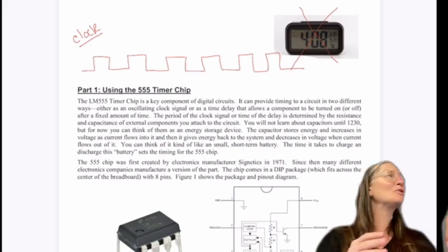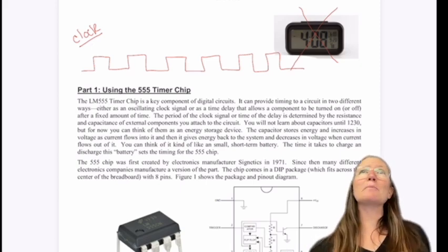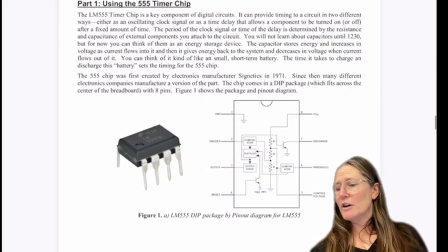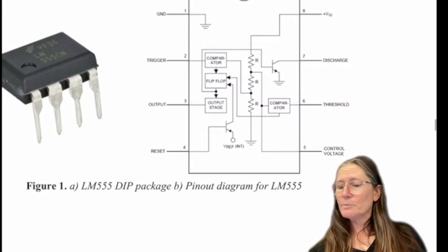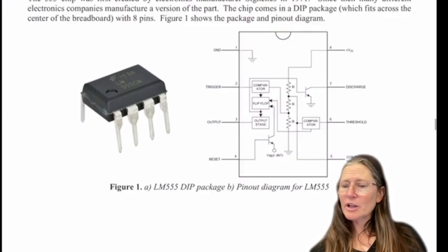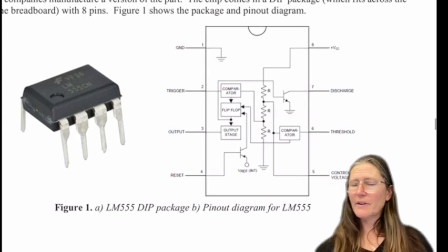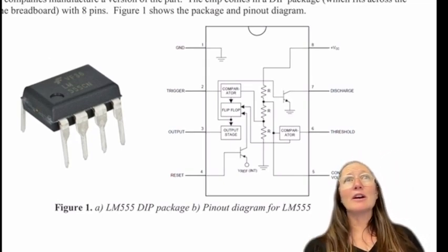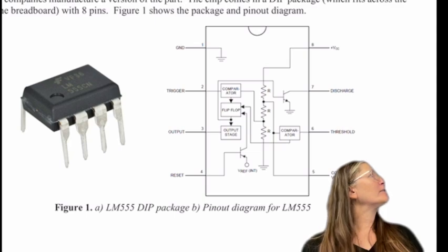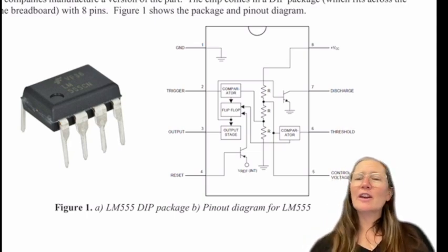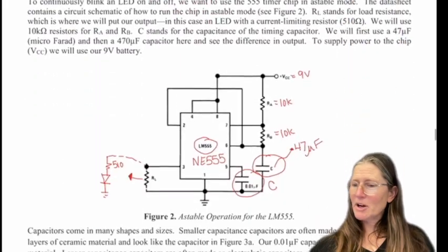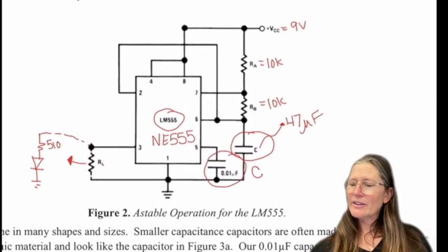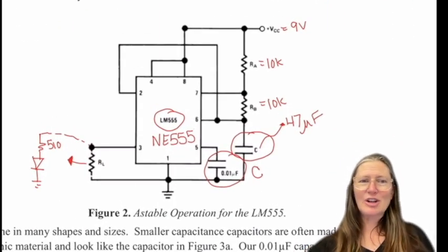So they're useful chips, so I wanted to describe them and go over a little bit how they work. These came in your kit, so it's an LM555. Today we're going to actually simulate them. And in the data sheet for these, they gave you a nice drawing already that says hook it up like this to create your clock.